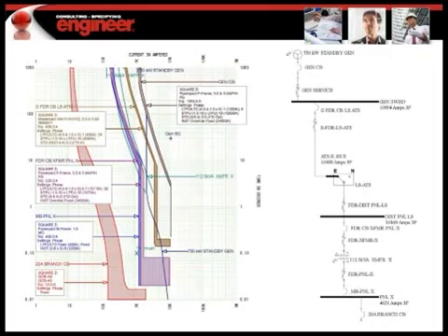And so here you see this set of curves indicates that the system is coordinated. As Jim pointed out earlier, we had to make sure that our generator curves, our circuit breakers fell to the left of the damage curve of the generator, and it does as shown in this diagram.